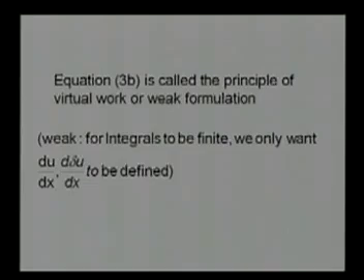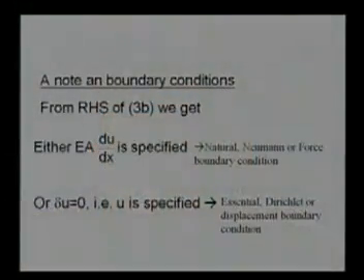So we may go ahead with that formulation, but they both mean the same thing. Okay, let us now concentrate on the equations that we have obtained earlier. There you see that we have this pair EA du/dx and delta u or w occurring together, and we said that if the force is specified, we let delta w or delta u or w be anything, and when the displacement is specified, we are going to set delta u or w equal to 0.